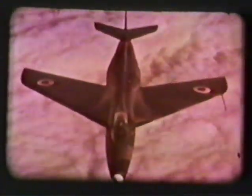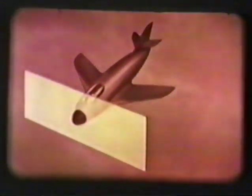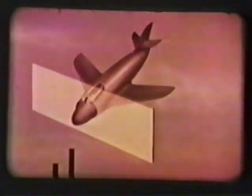Still faster flying is only possible when wave drag can be reduced. The drag caused by the shock waves changing kinetic energy into heat. A new design principle helps to do this. Area rule. Consider this aircraft. Take a section through it at right angles to its axis. So. Represent the cross-section on a graph. Do this at points all along the axis.